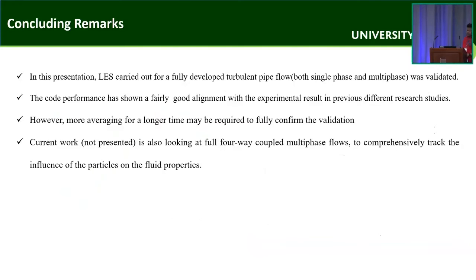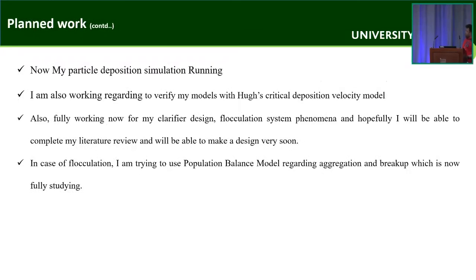So in this presentation, Elias carried out the fully developed turbulent pipe flow, both single phase and multiphase, was validated. The code performance has shown fairly good alignment with the experimental results in previous research studies. However, I always say that more averaging for a longer time is needed. Current work is also looking at four-way coupling, that I already told, to comprehensively track the influence of the particles on the fluid properties. So now my particle deposition simulation is also running.